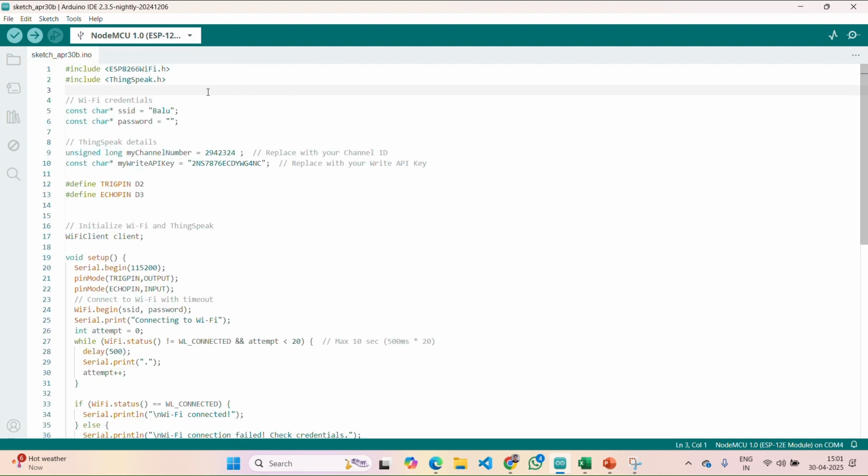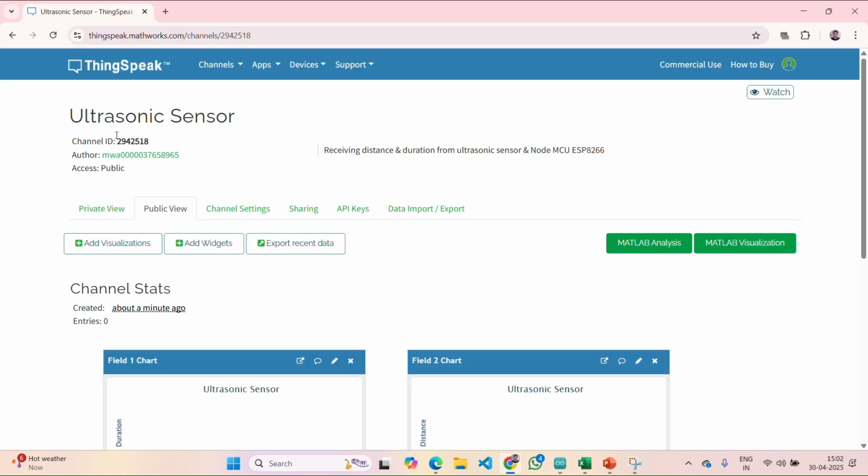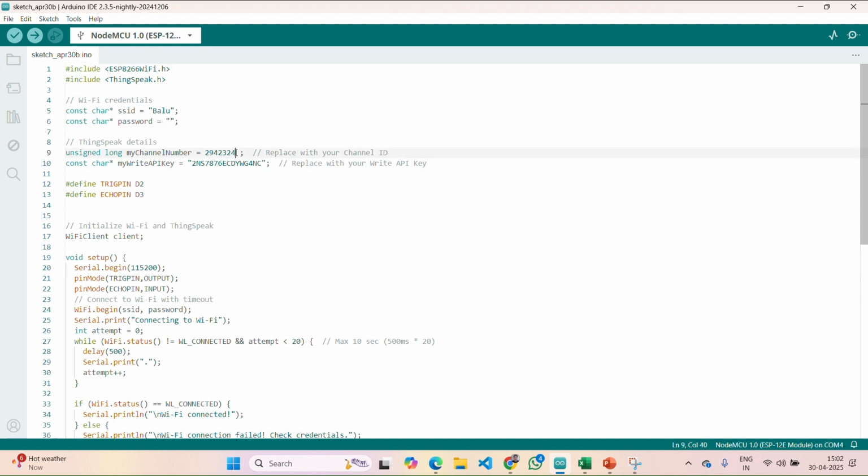Here we do not require the DHT.h file because we are now working with our ultrasonic sensor. Remember that, guys. Then Wi-Fi ID and Wi-Fi password. Coming here, channel ID and API key. This time I need to change them because those were for my DHT. This is my channel ID. Copy this and update it here as the channel number.